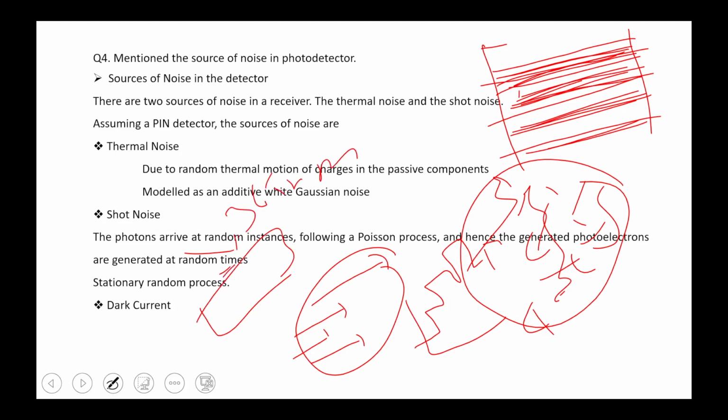If some ambient light from the atmosphere falls on that photodetector, it will generate some disturbance in the signal of the 365 nanometer light, or due to some external electric field, it will generate more dark current.